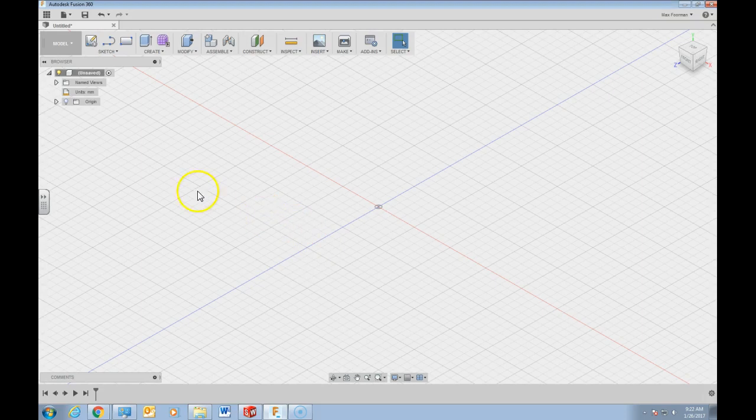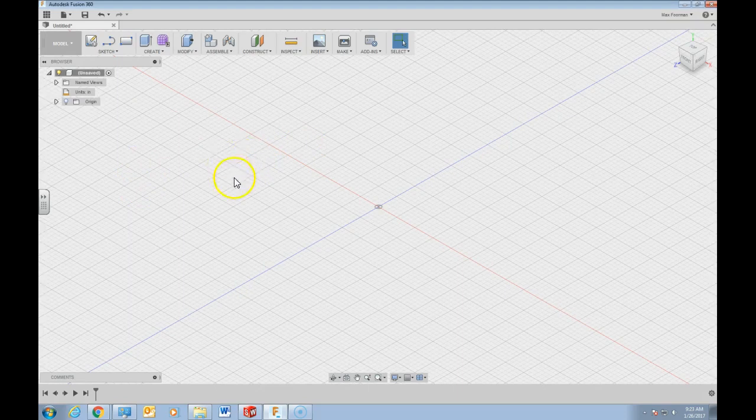So first things you're going to want to do right now as well, notice that units right now, likely yours are default set to millimeters. If you see this right here, similar to what I've got there, units mm, you're going to want to hover over this change active units icon, which is a little piece of paper with a pencil, kind of indicates edit. Click on that once, come down here, go from millimeters to inch. Mine is set to default inches normally, yours may not. You may want to click on that to try and set yours as default for the future. We're in America, we'll use inches for now, but we could fool around in millimeters later on other projects. But for now, click OK. Now we're in the correct units here.